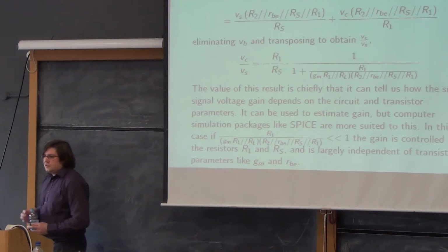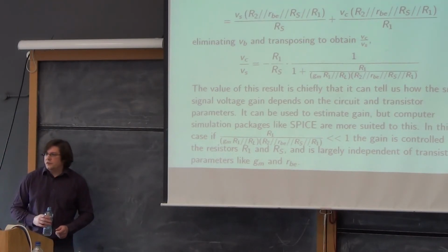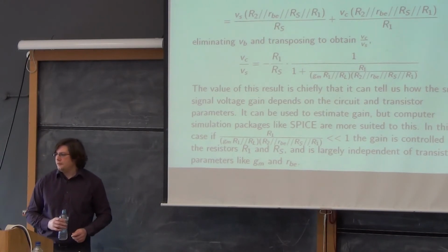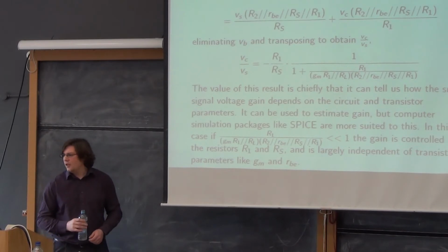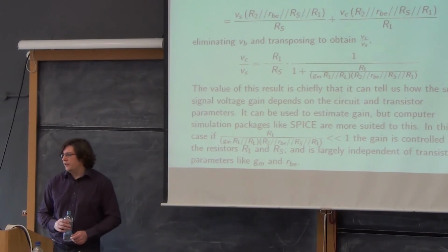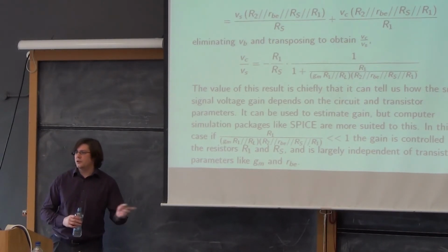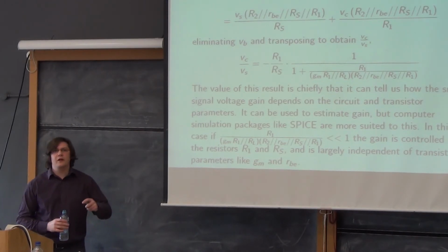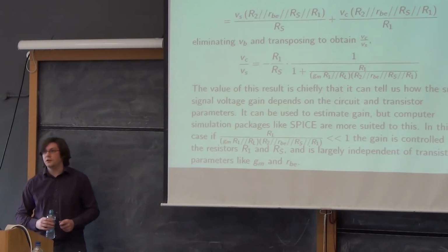So, as we transpose equation 1 into equation 3, we can transpose equation 2 into equation 4, and what I've done here is I've solved it for Vb. And I've left all the 1-overs because they're really just conductances now. And that expands, if you want to expand it, into a term in Vs, which is the first term on the left, which is Vs times a load of stuff in parallel on Rs, and Vc, which is our output voltage, because it's the voltage swing on the collector, times a load of stuff as well.